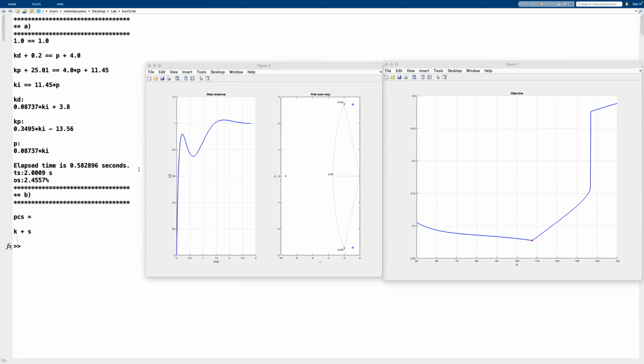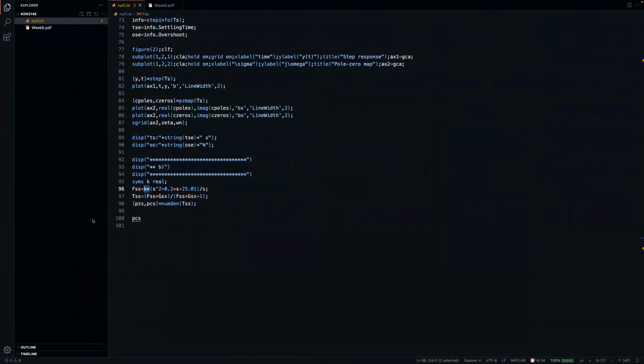So if I'm going to satisfy at least one of the specifications, which is the settling time in this case, because I cannot obtain any overshoot since the closed loop is a first order system, I should basically choose maybe k equals 2. That would give me roughly 2 seconds of settling time. So let's choose k equals 2. Therefore, our controller is ready.